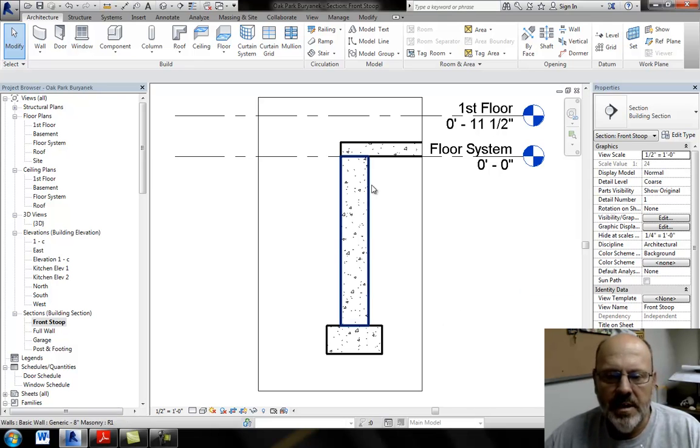So we're going to add a few details to this. I'm going to put two little dots in here that represent the number 4 rebar, and then I'll put a couple of them up here, and I'm going to put a thick polyline going up. It'll stick out of the stem wall a little bit up into this slab, so that anchors it together. Go down here into the footing. So there will be a pin that's put in the footing, and then a wire tie for another piece of metal that goes up. We'll just represent it as one continuous piece of steel.